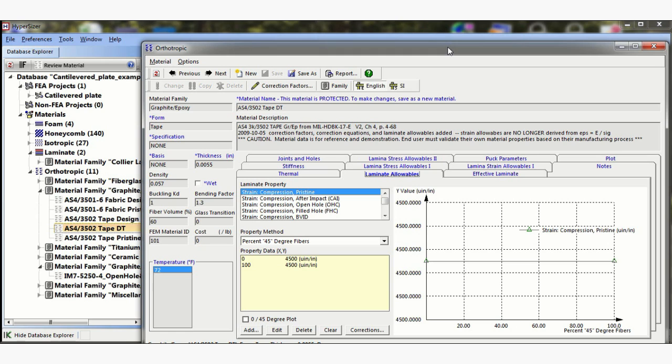But once we incorporate damage, impact damage, and open hole allowables, calculating allowables on a ply-by-ply basis just seems to be not appropriate. So some corporations use laminate analysis and they use laminate allowables, and they make their models a little bit differently.